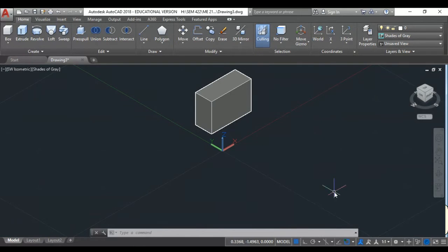Now, if I'm asking you to tell me how the top view will look, then you will go and look at which plane, guys? YX or XY, right? Now for the left side view, you look at the ZY plane. Clear, guys? Okay, I just need you to get acquainted with how these directions are related to the three views that we dealt with before.